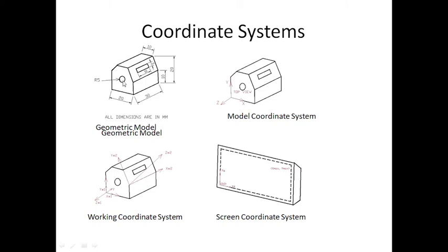How you make this hole is, it basically refers to this surface patch of this model after you generate it, and on top of that you generate this rectangular sketch. This rectangular sketch is made with the help of two reference edges, this one and this one, so that you can properly locate this sketch and then extrude it or make an extrude cut. Similarly, this one is referred with respect to this line and this line, to locate it.